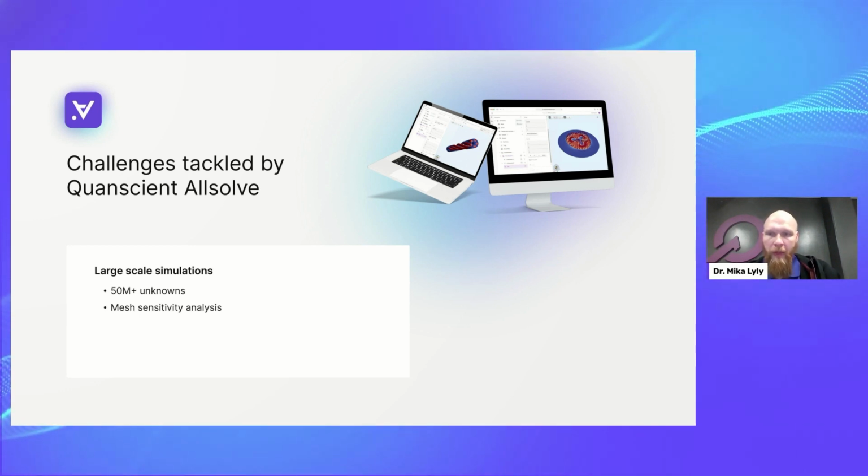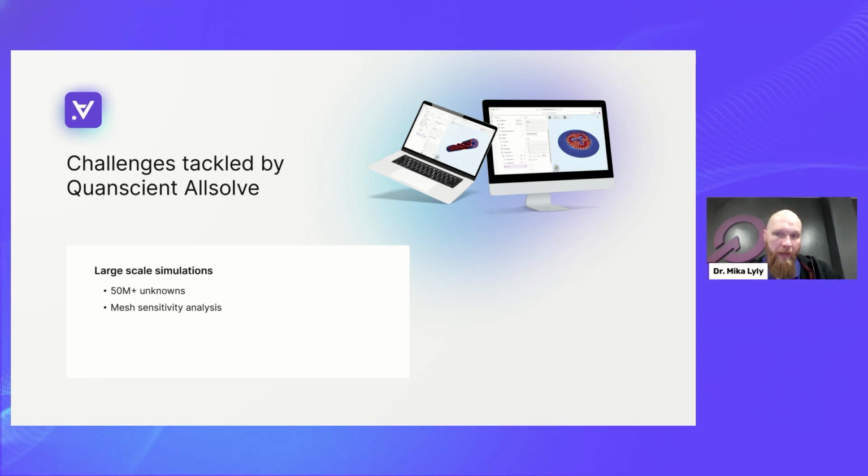And these kind of problems you can face typically in case you have a very big geometry. Naturally, you cannot exploit any symmetries, or you want to do a mesh sensitivity analysis for certain geometries, then you may easily end up with very large scale simulations. As well, if you have a high aspect ratio between different objects in the geometry.